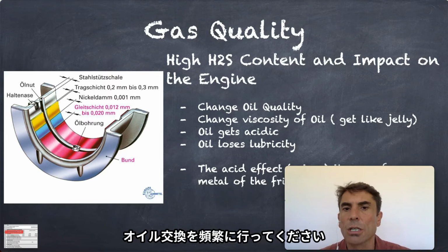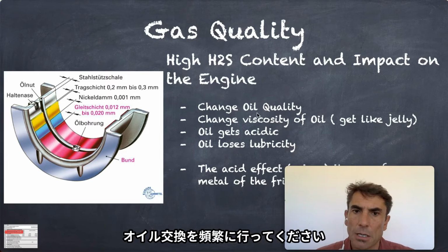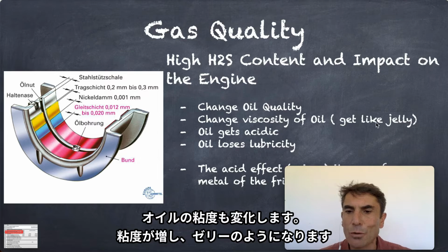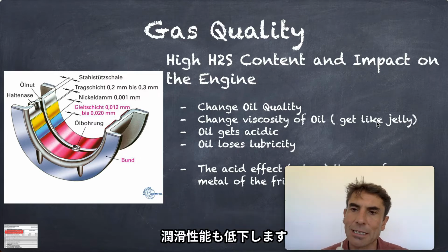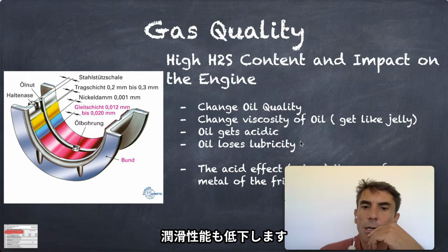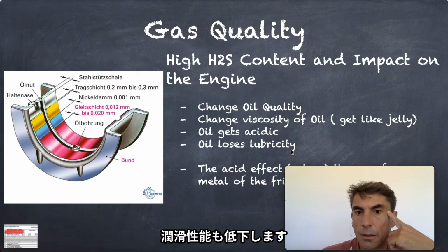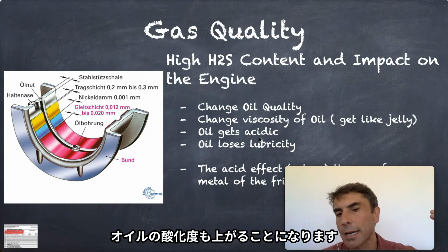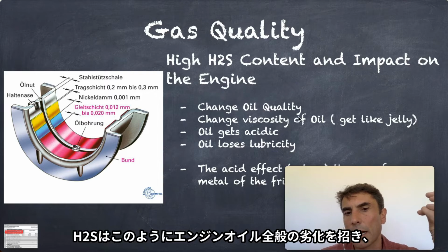So it's changed the quality of the oil. The viscosity of the oil gets changed as well. It can get up to like jelly. So the quality of the oil changes, and yeah, losing lubrication. And the oil can get very acidized from the H2S content. So the H2S has all the impact on the oil quality.